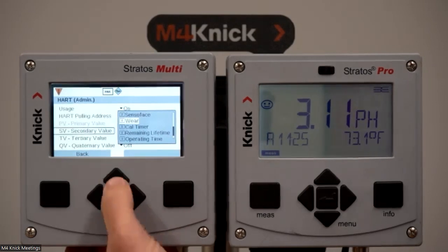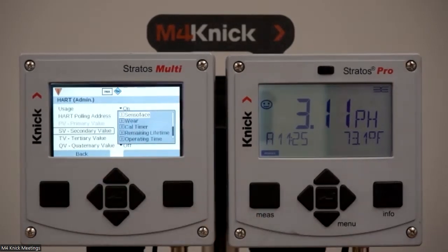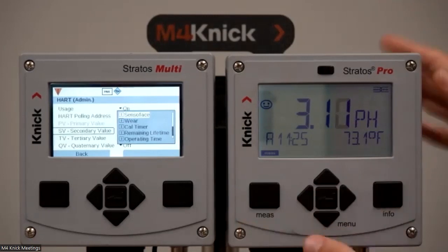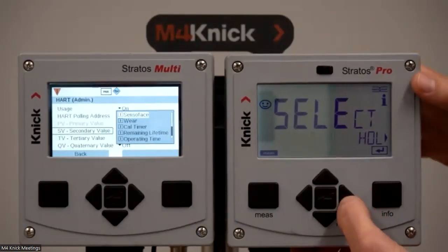As you can see over here with the Stratus Multi, we can assign the Senso face to a HART variable or to an analog input via Ethernet communication protocol. The way that would look back at your control system, it would come through as either a 0 or a 1 or a 2, which would be tied to, is the Senso face smiling? Is it a neutral face or is it in frown? Very high level, quick indication, but of course, if you're not utilizing a digital protocol, you would need to have somebody view that locally. Further, if they're there locally, they can dive into the diagnostics when using a digital sensor.